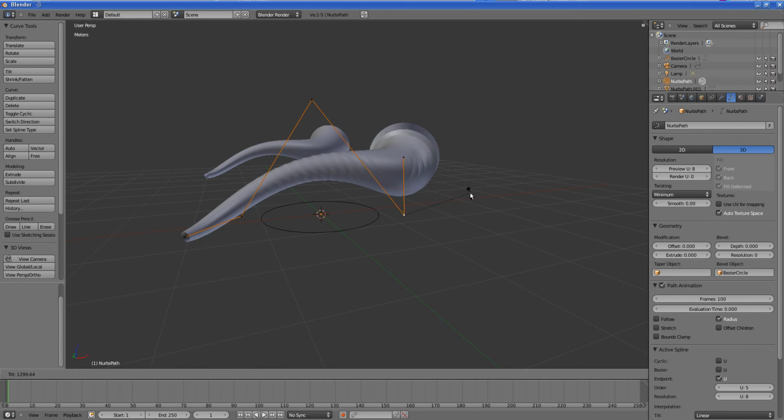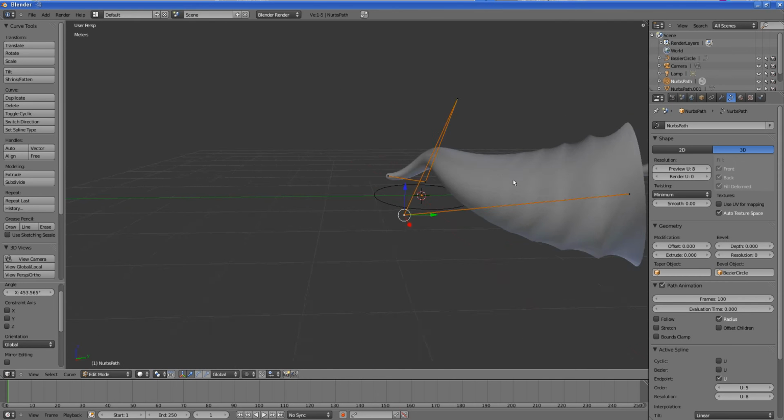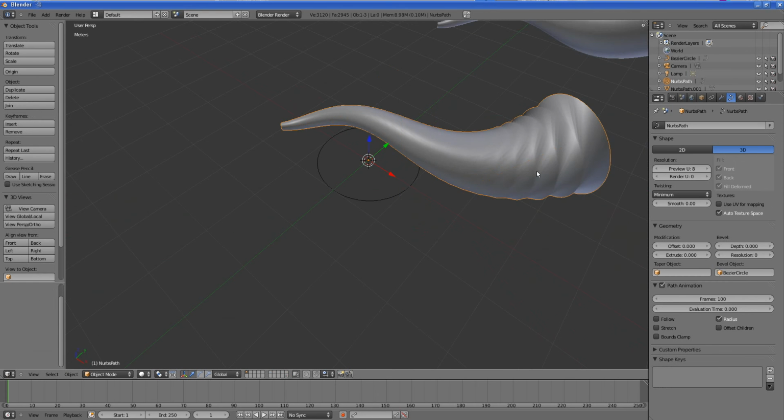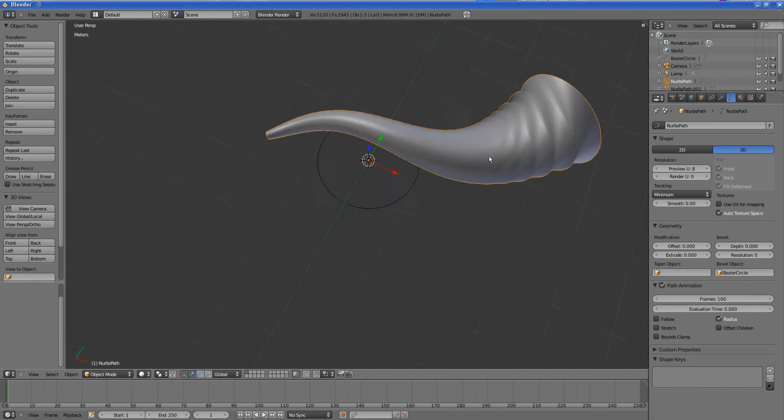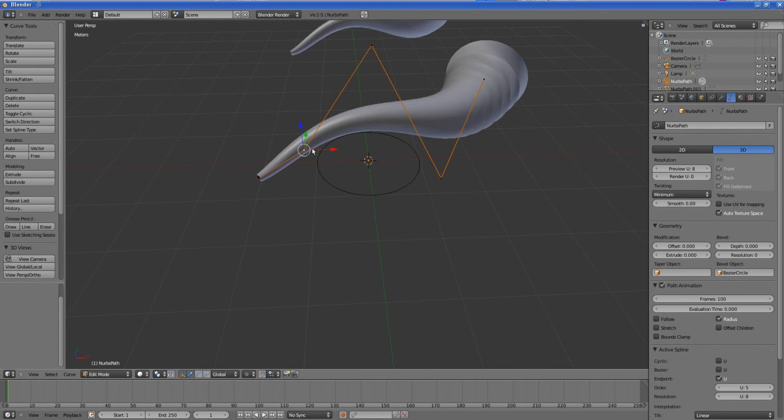As you move the mouse, you will notice the control vertex is tilting, and as the curve follows along these control vertices, it tilts, and you have this sort of twisted behavior. So let's select this vertex and Control T, and just move the mouse around, and there you go.